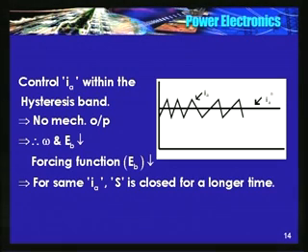So see that there is a change in the switching frequency also. Current increases slowly, decreases faster, because here Eb is falling, the forcing function has fallen. Now the voltage across the inductor is VDC minus EB, EB is falling, VDC is held constant. So voltage across the inductor increases as omega decreases, and decay is faster.